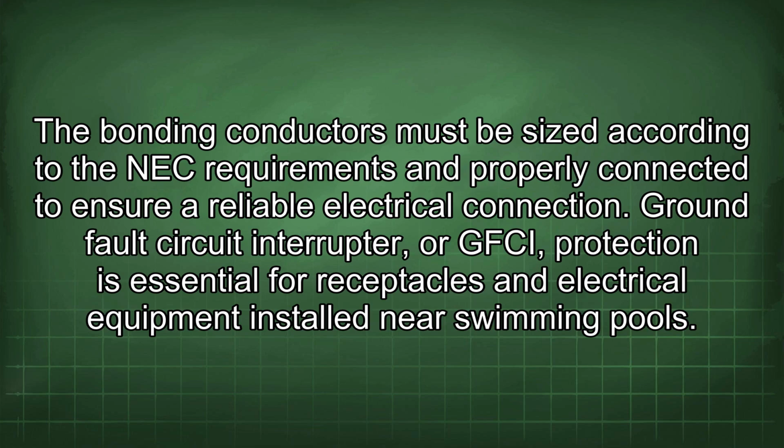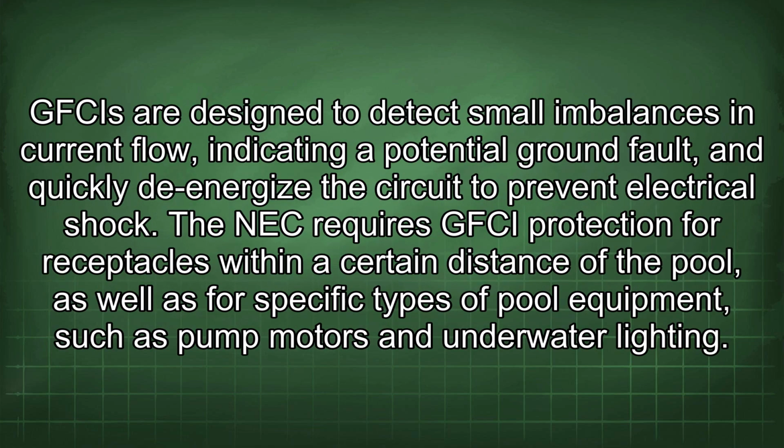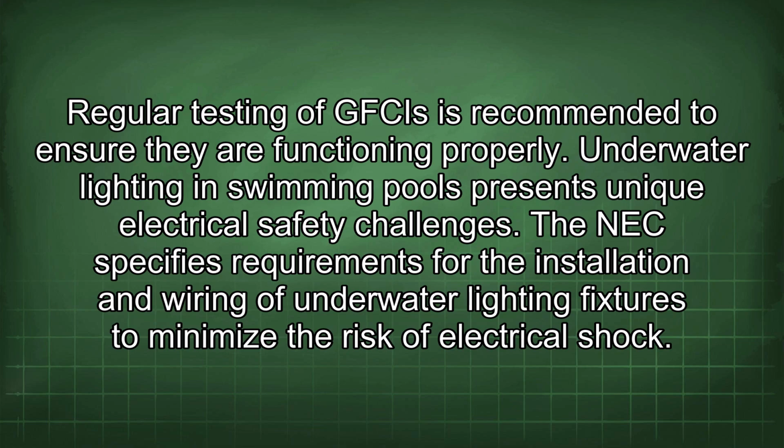Ground fault circuit interrupter, or GFCI, protection is essential for receptacles and electrical equipment installed near swimming pools. GFCIs are designed to detect small imbalances in current flow, indicating a potential ground fault, and quickly de-energize the circuit to prevent electrical shock. The NEC requires GFCI protection for receptacles within a certain distance of the pool, as well as for specific types of pool equipment such as pump motors and underwater lighting. Regular testing of GFCIs is recommended to ensure they are functioning properly.